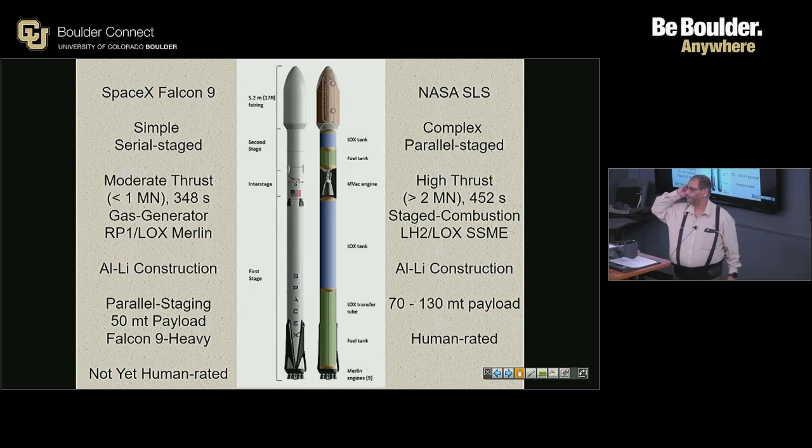They use the super-cooled liquid oxygen that can only be kept in the rocket for so long before it expands and has to be redone. Yeah, the fill time is less than 45 minutes. So you have to have the vehicle filled with propellant in about 45 minutes and launch. Now, if it takes another hour for these astronauts to get in and make themselves comfortable, the advantage of super-cooled propellants is gone.